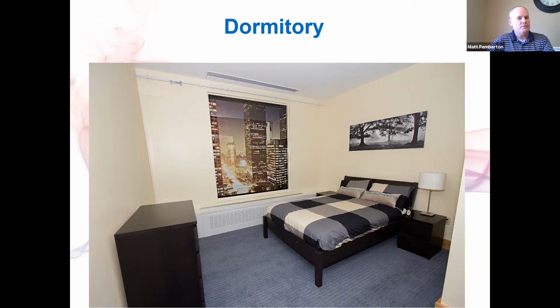And so the big benefit by far is that big, huge dedicated outdoor air system pumping air up and down all the floors at very high statics. We change all that. Instead of running 2 inches of static, we run it at 3/4 of an inch of static. So huge energy and fan horsepower consumption savings. Well, back to the future.